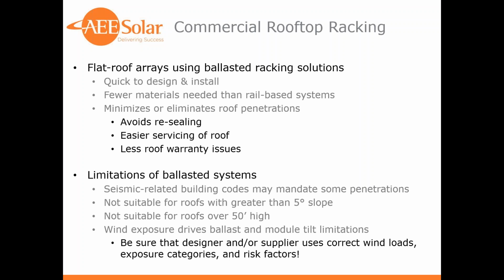Yes. Okay. So the ChemLink E-curves is an excellent solution to seal penetrations on most roofs. Also, we've had great experience recommending Anchor products or OMG Power Grip Plus for the seismic anchors for TPO and EPDM and other roof surfaces.